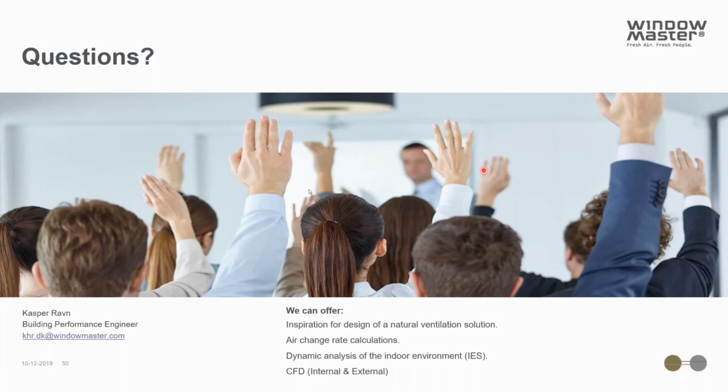Typically, when we have a mixed mode system with mechanical ventilation during the winter, we want to, of course, take full advantage of the heat recovery. And in almost all cases, you don't want to use the windows while the mechanical system is activated.